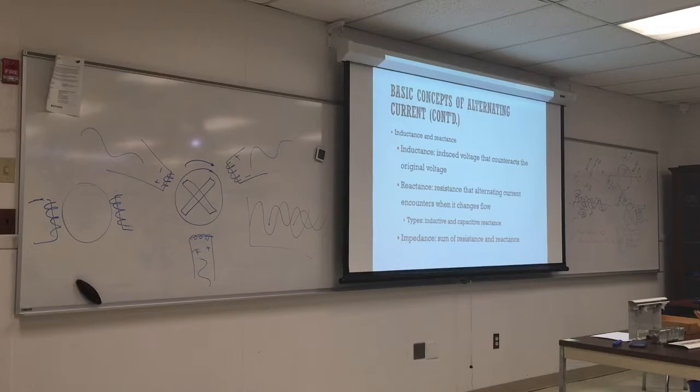It's not necessary. You'll see it either way. But what do you think is one reason that you put the winding on the stator? You just have to guess. So it doesn't move. The rotor is moving at like 3,600 RPM. It's easier to leave the stator with the winding intact here instead of moving it the entire time.